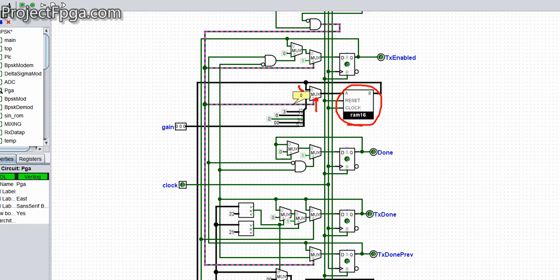So you can see this is RAM, 16 bits of RAM. It means 16 flip-flops together. So that is how the gain of the amplifier is programmable. That's how we set it here using this multiplexer and this RAM. The RAM latches it. We are going to see how we use it.